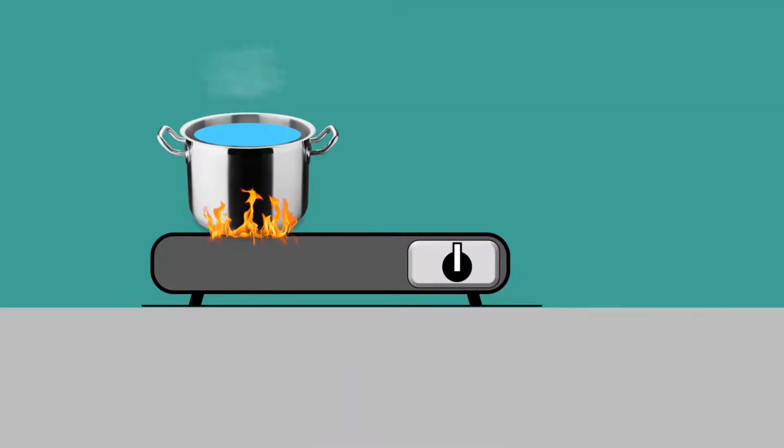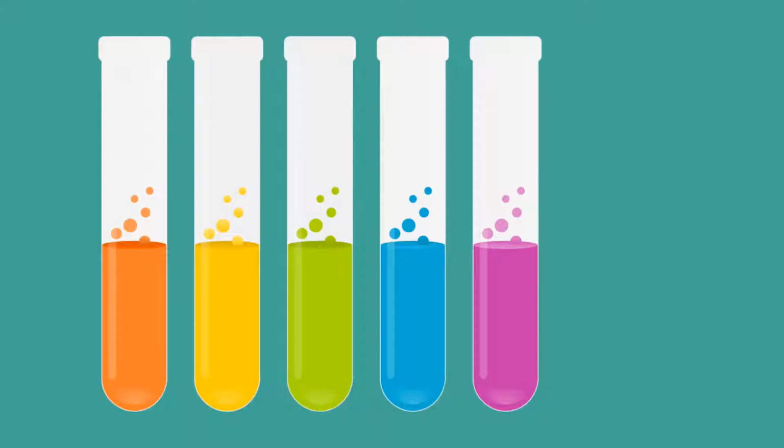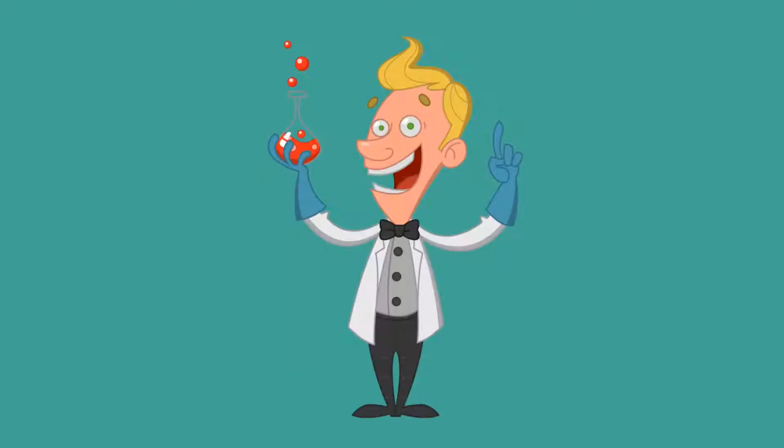We need some method to produce steam. For what purpose? We need steam to run the turbine. That doesn't mean that it should be water vapor. It can be a vapor from any liquid. We have lots of other liquids. Different liquids have different boiling points. If we can find a liquid whose boiling point is very low, then we can replace this low pressure seawater with that liquid. The best suitable liquid here will be ammonia.